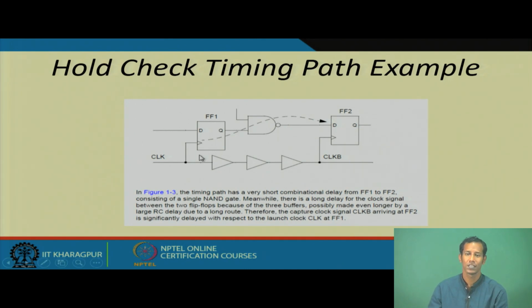Why? Because when you synthesize a digital IC core, all the sequential elements are not placed in one particular place. They are distributed all over, in all the corners of the core, and your clock source comes in through one particular location. From that location you have to distribute the same clock to every sequential element present in your core. This distribution requires the clock tree network, or clock tree synthesis.